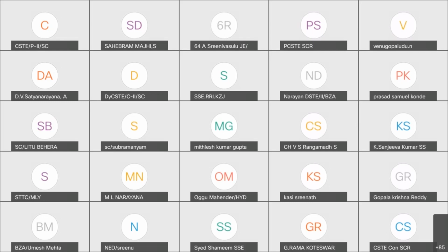Actually, it is as per the power consumption requirements, sir. In the normal layouts, the points are operated parallelly because the load current taken by the point machines simultaneously will be within the power supply range of that particular station. But in the major layouts like RRIs, if all the crossovers are allowed to be operated in parallel, so much instantaneous load will be on the power supply side, sir. So the power supply capacity requirements will be double. To reduce this, we will go for a series operation in the major yards like RRIs.